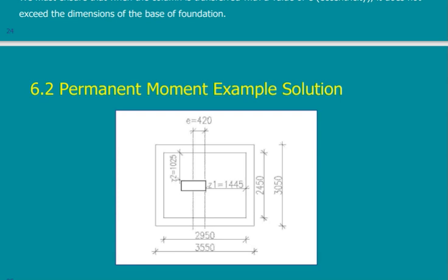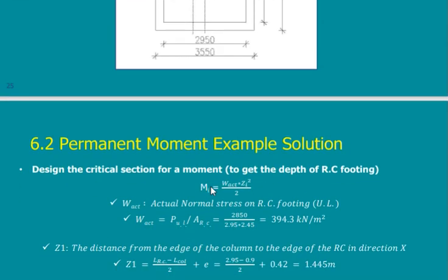So in this case, this footing can be subjected originally to two moments, and by doing eccentricity in X and Y directions, I can cancel both and I end up with a footing as if it has no moment, but the column is shifted in two directions. Or in one direction, it depends on my example.